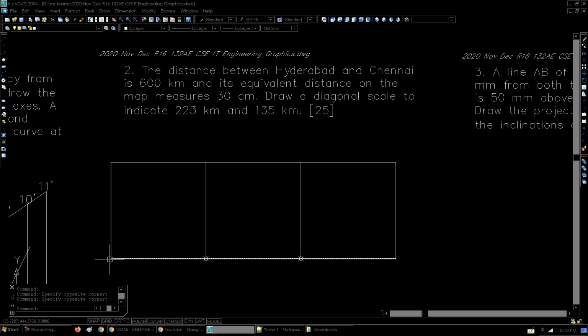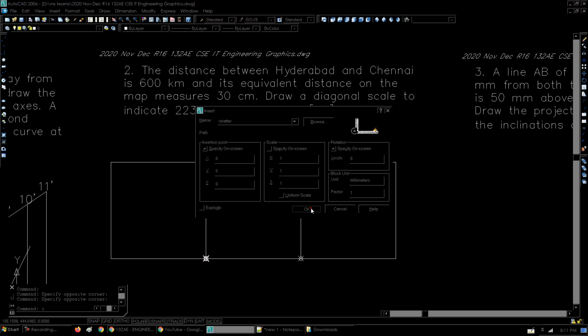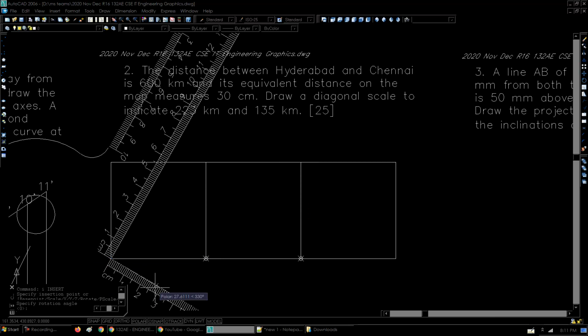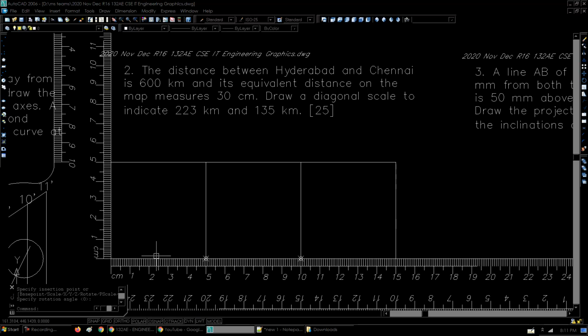Okay, let's go ahead to the subdivisions of the scale. Each of these divisions measures 5 centimeters, and we are supposed to divide this first division into 10 subdivisions. Now 5 centimeters can easily be divided into 10 parts, and each of these parts is going to be 5 mm. So once again you can just take up your drafter and easily make these 10 divisions.